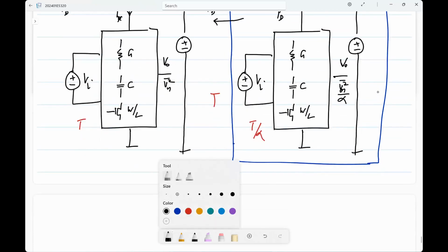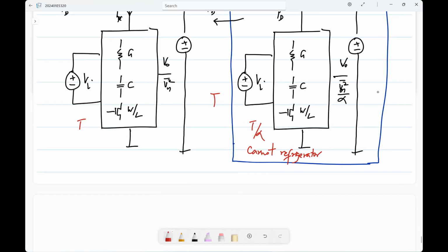So this, of course, is the, I don't know if it's called the Carnot refrigerator, but it's just exactly a reversed Carnot engine. Now, anyway, this is not such a crazy idea. We don't do it in consumer electronics. You don't want to build a fridge around your cell phone just because you want better reception. But for circuits that need very low absolute noise, like very sensitive measurements, let's say radio astronomy, because you're receiving signals that are so weak, there are actually cooled receivers. Of course, that's used in niche applications where you need very, very low noise.